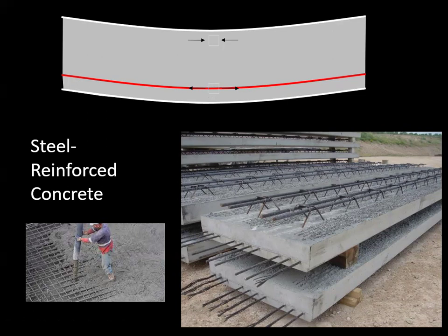So if you just had a concrete floor with no rebar in it, it would just crack apart and fall apart in like 2 years. You might be lucky for it to last that long. But you throw in the steel, that steel rebar, now that can handle the tensile strength. Is that right? Now again, to round this back out to thermal expansion, this material only works because steel and concrete expand and contract at the same rate.